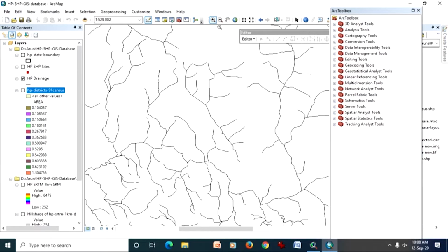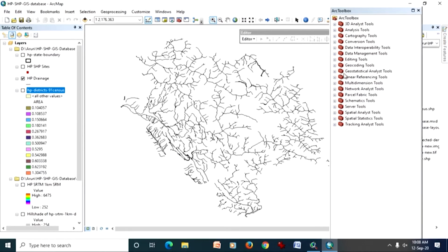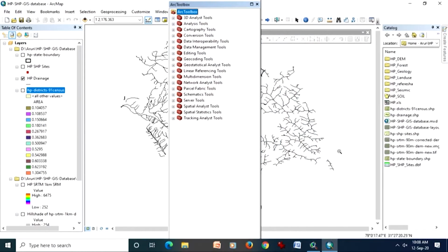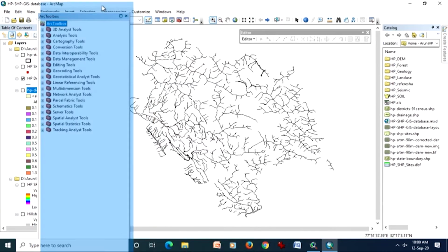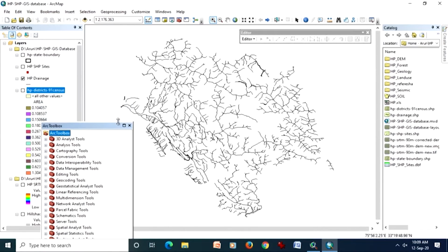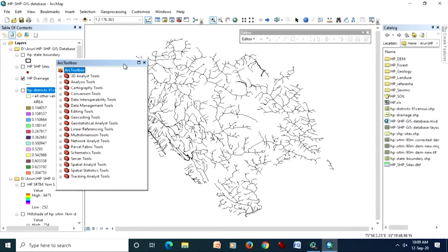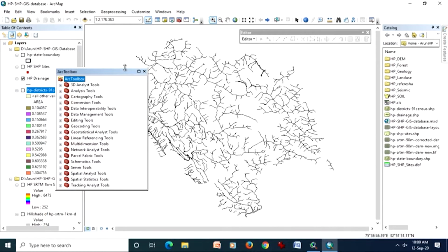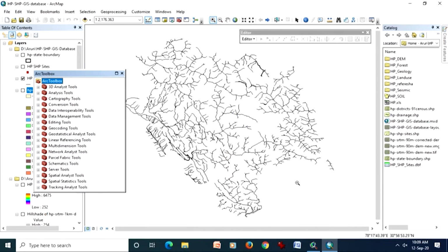You can zoom in, zoom out, and also if you see here, when my cursor is moving on this map in the ArcMap view, the latitude and longitude are also changing at the same time. As we have been discussing, every data is organized in a geographic coordinate system, and therefore though the data is in decimal degrees, the system can very easily display it in the form of degrees, minutes, seconds, so that we can compare with other data sets.